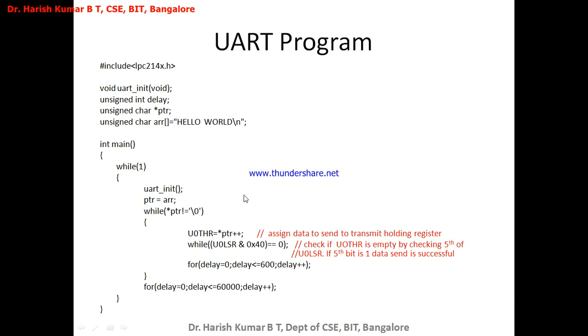So this is the program. I hope you understood the program, and I have written the comment also here. Check if U0THR is empty by checking the 5th bit of U0LSR. If the 5th bit is 1, data send is successful. If it is 1, data is already sent. If the 5th bit is 0, data is not yet sent.